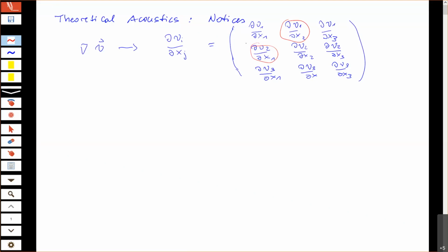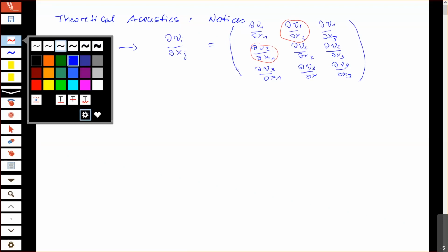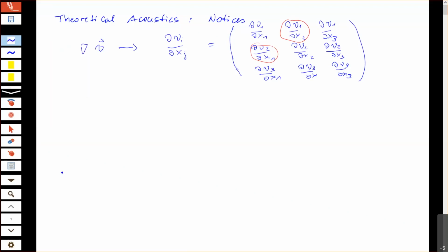And a second thing I want to show you, which we already had in our equation, is the divergence, where we write a second-order tensor in brackets, the viscosity tensor. Here it is clearly easier to write this in index notation, so tau_ij with respect to x_j. And what we already know is that when you take the divergence of any tensor, you reduce the order by 1.